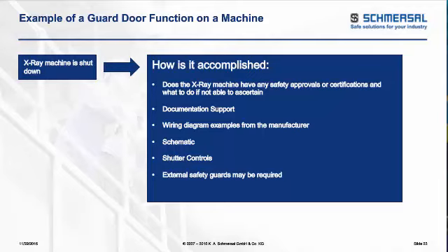A lot of those peripheral controls may not have safety approvals that claim a certain control category for their controls. So how do you safely operate those machines and meet what your design intent is, based off of your risk analysis? Again, it could be very difficult, because if the controllers don't have safety approvals, many times what you have to do is turn off the main power to that particular unit.